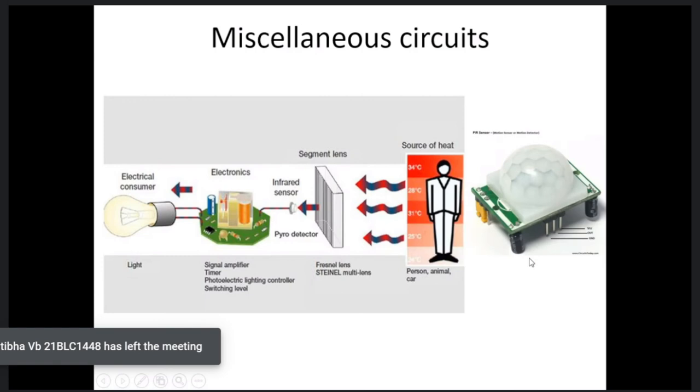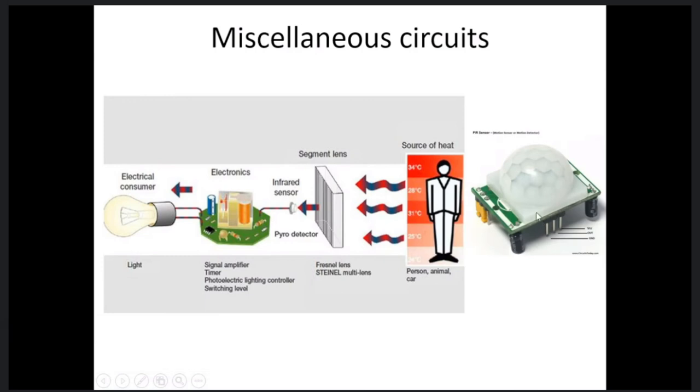When someone enters, as I said, proximity sensors work with changes in the electromagnetic field actually. So that is the inductive proximity sensor. Similarly, passive infrared sensors work with changes in the temperature. It will radiate and it will receive the temperature also. But when a human enters, it falls over the human body, and it gives the variation in the temperature. That is the sensor we are using here. So you can switch on the LED light.